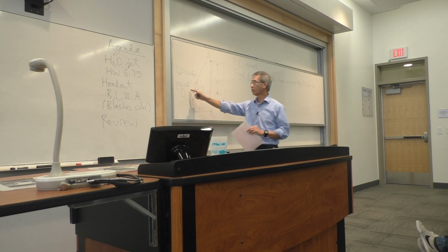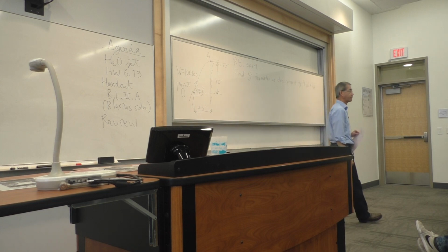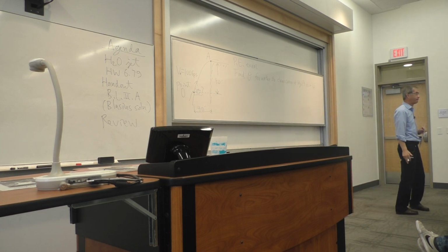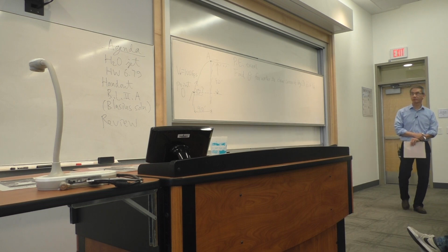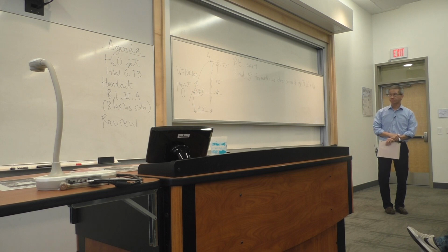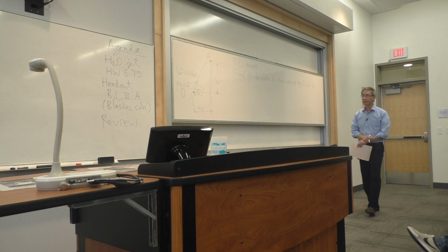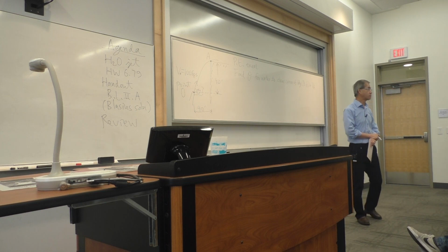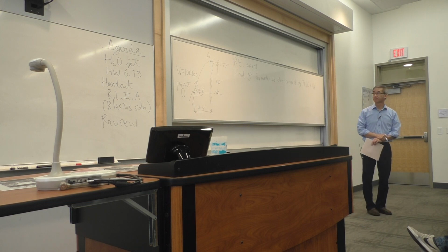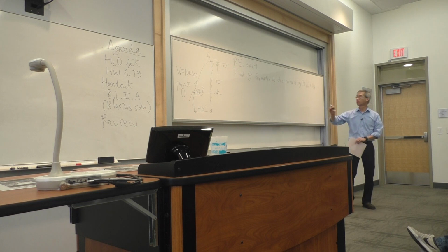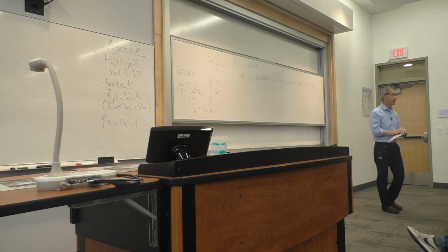So the origin point O starts from the exit of this water jet. And you are told the velocity of the jet is 100 feet per second. It's 40 feet horizontally from a building and 50 feet height from the top of the building. What I want to know is what orientation, angle theta of the water cannon will allow me to clear the point A. And upon doing that, I also want to find out the velocity at that point A.